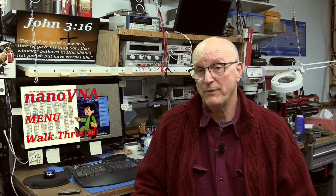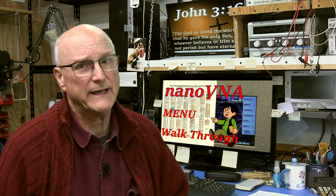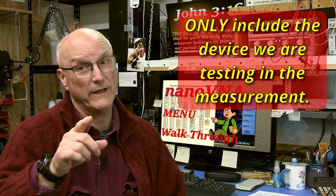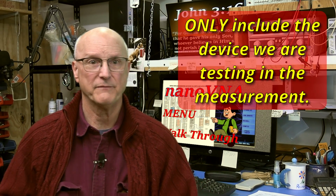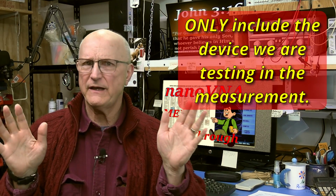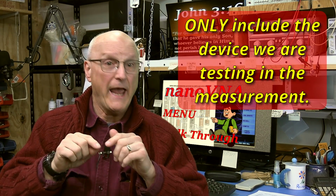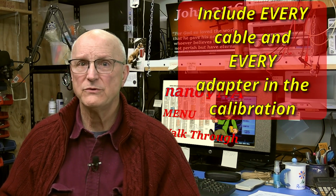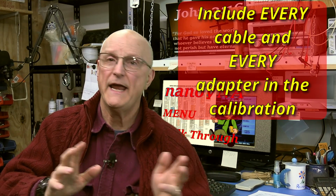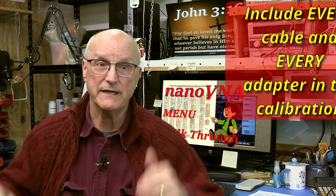Now we're ready to begin the final preparations for our measurement: calibration. The key to remember when doing the calibration is that we only want to include the device we're testing in the actual measurement. Any addition of cables or adapters between the device under test and the VNA after calibration changes this. We want to include every cable and every adapter we use in the calibration process.